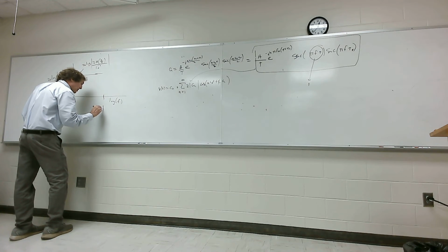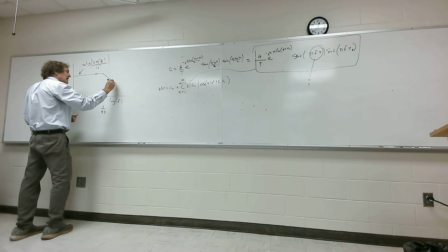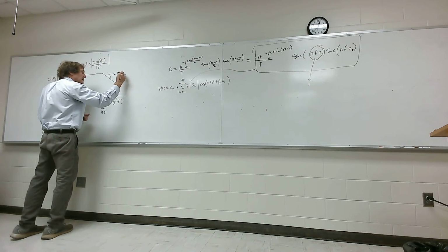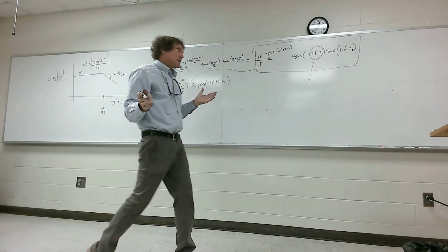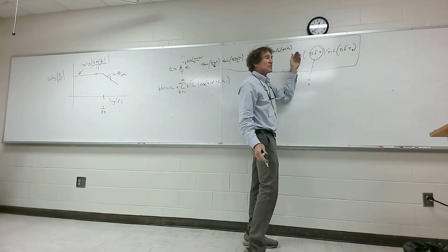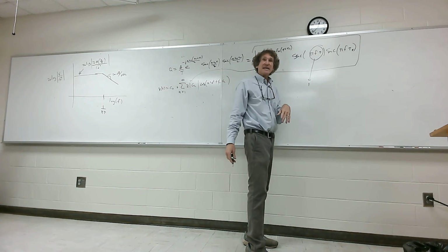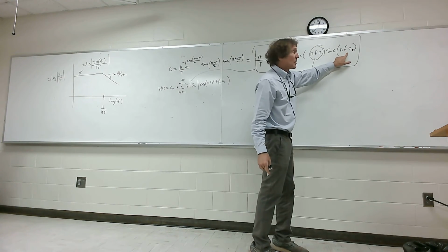So this first frequency that breaks that is going to be 1 over pi tau. And it's going to start going down at a rate of minus 20 dB per decade at that point. With me? Just hang on. 20 dB per decade, because now this thing looks like simply a 1 over f function. And 20 times the log of that is just going to be minus 20 times log of f.